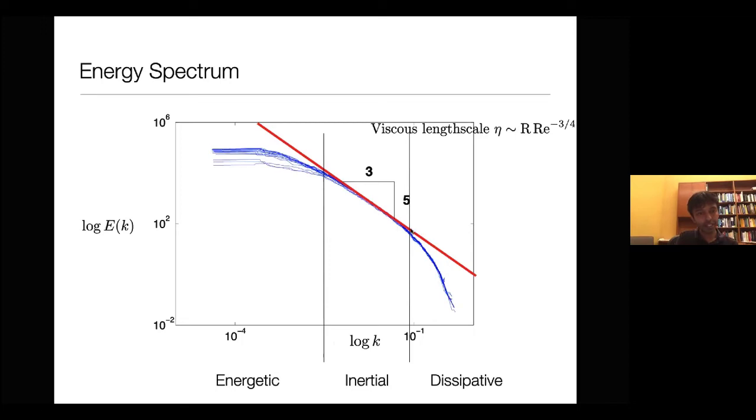And there is this region of intermediate size where you're not too large or too small. In this intermediate scale, what is called the inertial range, you do see energy spectra that conform nicely with a k to the power minus 5/3 slope. But as you go to large k, or small size of eddies, you have a rather rapid, almost exponential drop-off of the spectrum. This is the so-called dissipative region of the spectrum.